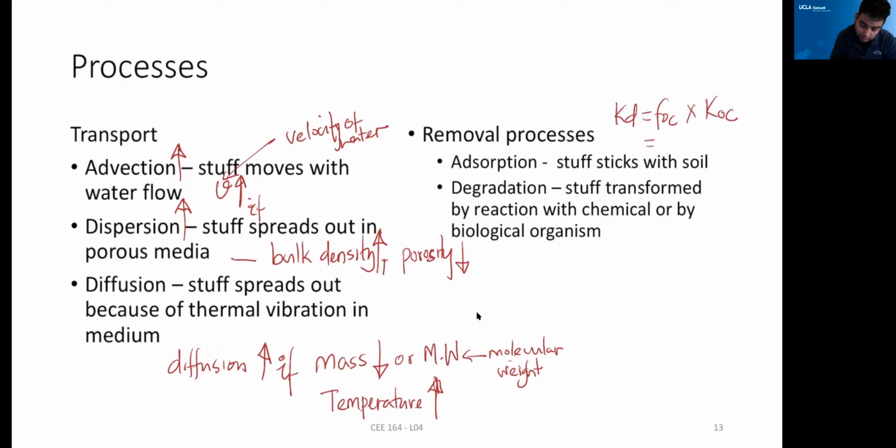And we also know that KOC, that means affinity of contaminants to our organic carbon, can vary with type of organic carbon. And we know that in nature, organic carbon can vary at different types. So that's why a lot of times experimentally they determine affinity of pollutants towards octanol. Octanol is a specific type of organic. So KOW, octanol water coefficient. So this is something you can find out if you Google it for any pollutants, and then you can compare between different pollutants which you have at your site.